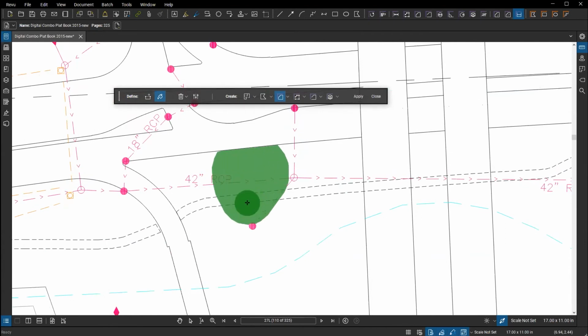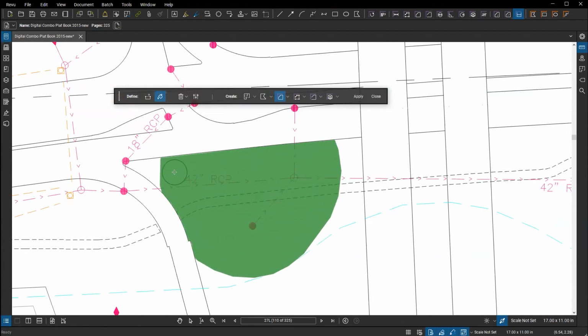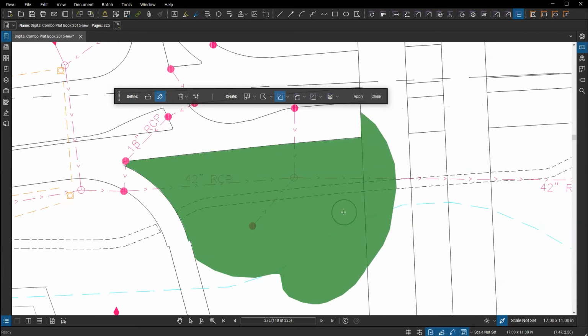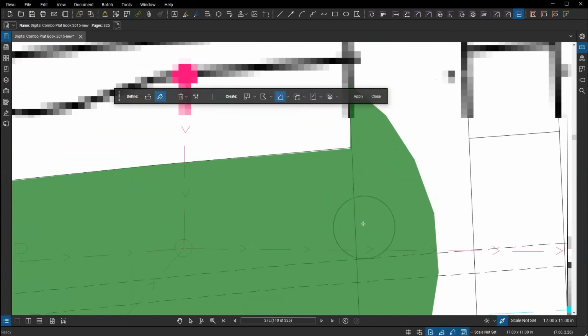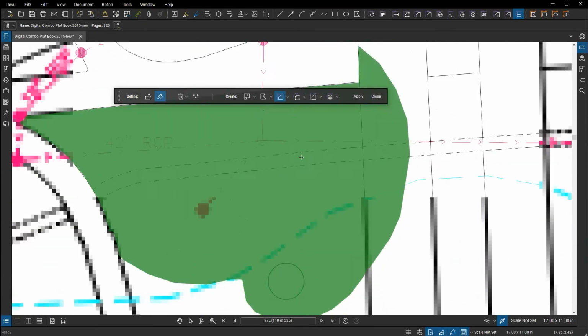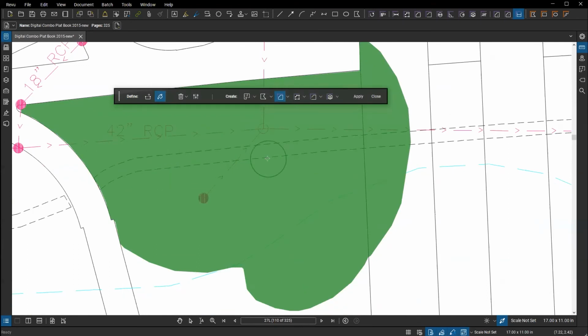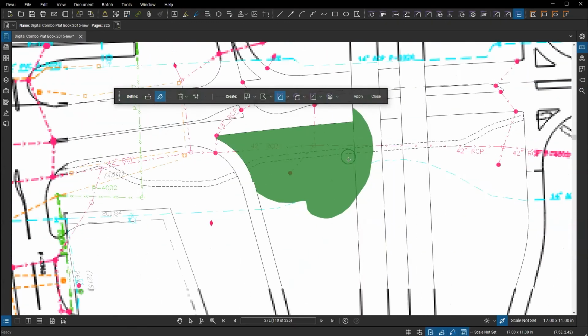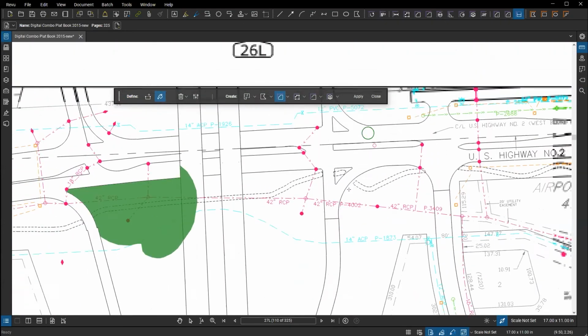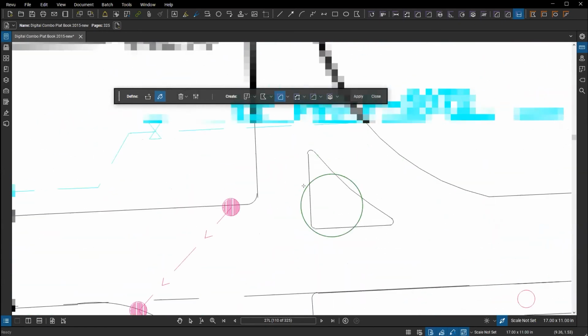And just press and hold. It comes in here and just fills these areas in that I'm trying to understand. Even the curve, it'll go through and fill around that curve for me as well. And what might be happening here is there may be some kind of an opening or a void. You can see here, this was a dashed line. It'll bleed right through anything that's not a continuous line. So I may just happen to grab the wrong spot, or the integrity here is not that fantastic, but I'm sure you can get the idea.